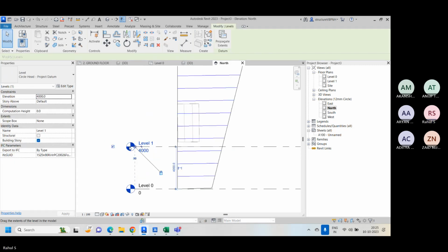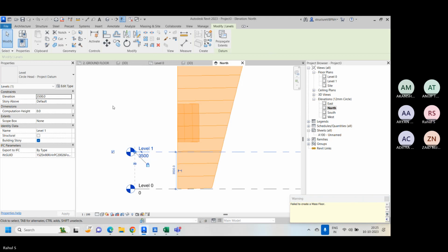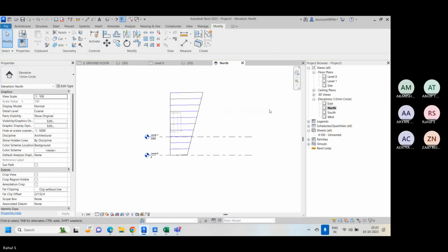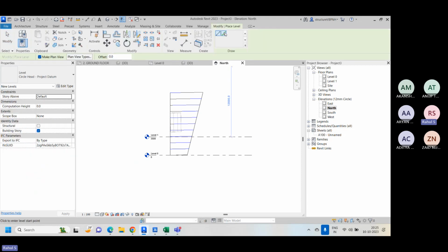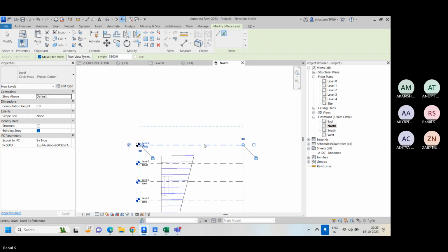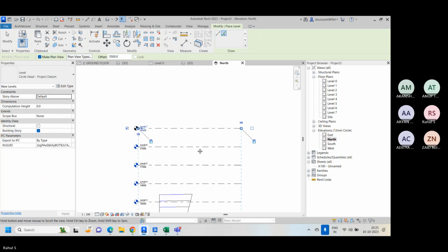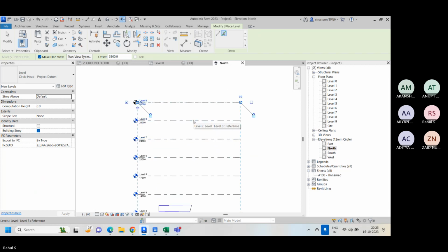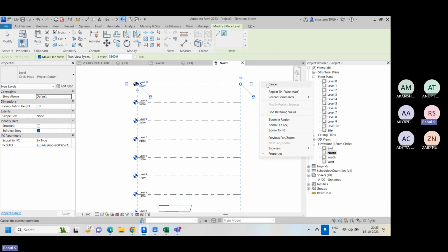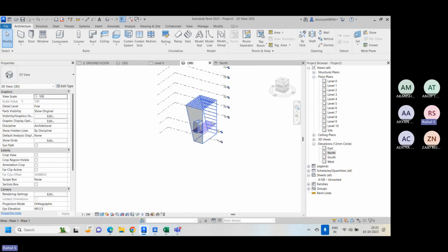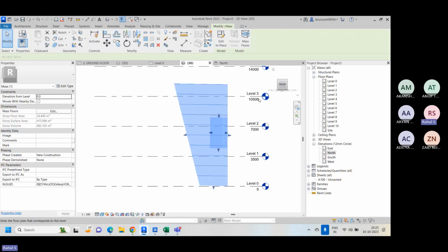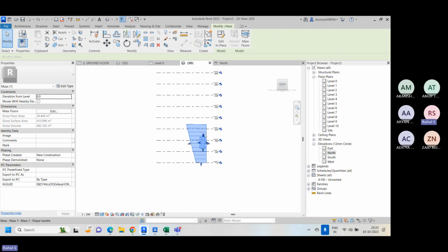We'll adjust the height first of all. Let's say 3,500, 3.5 meters, sorry. And on top of this, we will add a few layers at the same distance. Let's assume 10 floors for the time being, and just create this structure till the 10th floor.